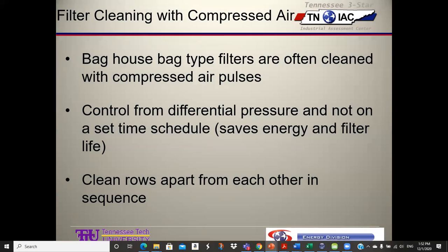So environmentally, it's okay. It could be pulling air conditioning or heat out with it, but if you have a process generating a lot of dust, you have to control the dust. And then the dust accumulates on the outside of the bags. And so every so often, there's a compressed air line, and it'll have a little solenoid valve, and it'll open and blow a burst of compressed air down on the inside of the bag, which then goes in the opposite direction through the bag and knocks that dust cake off, and there'll be a hopper or something down there to collect it.